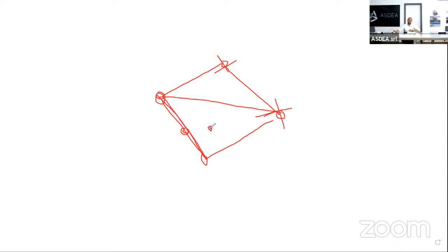If I am in the middle, there will be a difference, because a triangle can only represent linear displacement, while a quadrilateral can represent a bilinear displacement. So linear in this direction, but the cross product of them is not necessarily linear. So it can be like a paraboloid.